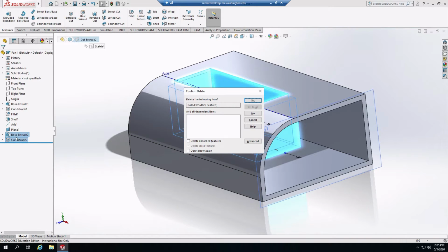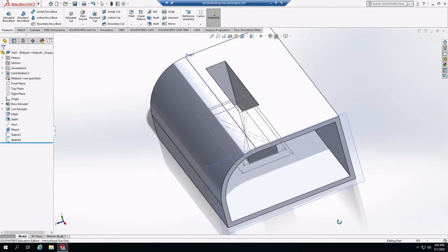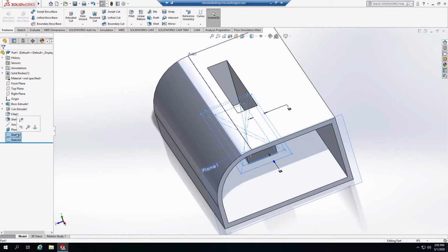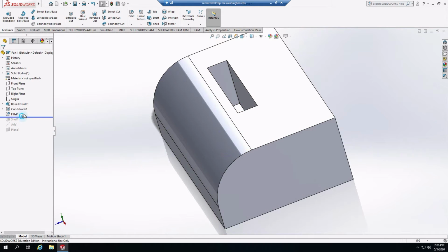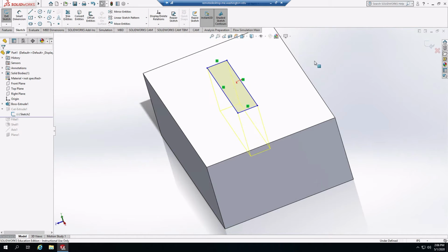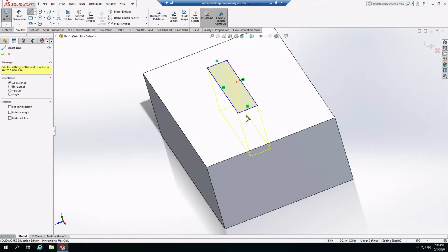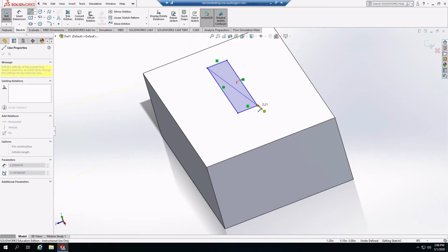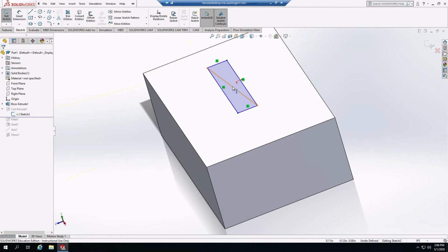Now let's say, for example, that this is too time consuming and we want to do this a little bit faster. What we would instead use is more of a parametric modeling. We would go back and look at an earlier feature, an earlier geometry, cut, extrusion, or whatever that we had defined, and we would change what we did in the past.